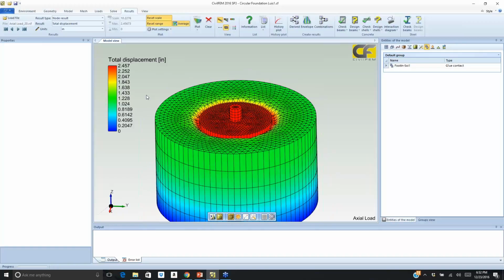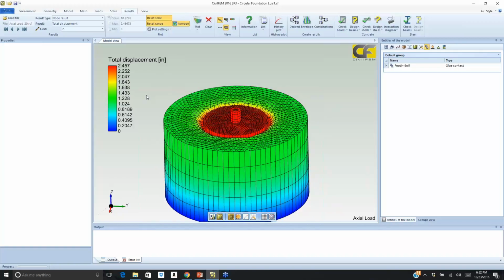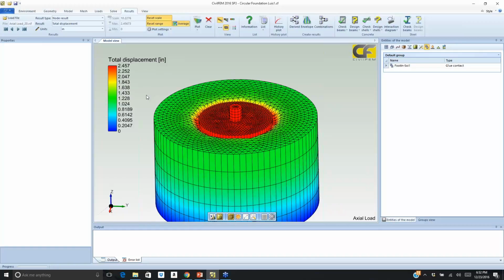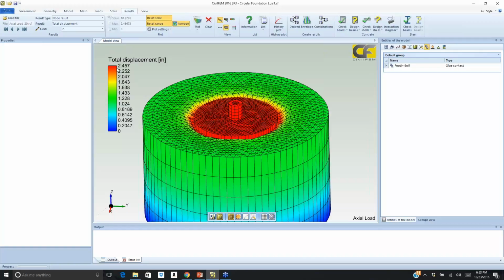Normally, you can have industrial piping between buildings, and this becomes a load for such a piping system, for instance. This vertical displacement is approximately 2.5 inches downward. We will also demonstrate the bearing load and compare such a load in pounds per square foot to the allowed soil pressure, which is normally 2,000 psf.